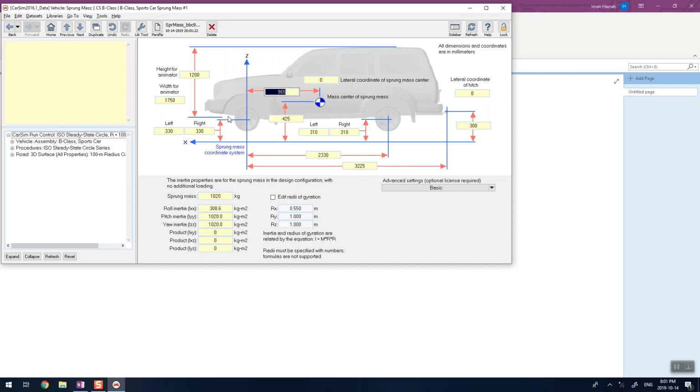You may notice that some parameters here are just for a graphical point of view, like the way you define the envelope for a vehicle to make animation around it. All of the units are in millimeters, and the total CG of the unsprung mass is here. I recommend taking a screenshot of this one, because you may need it for one of the questions at the end of the tutorial. And bear in mind that the reference coordinate system is assumed on the road and passing through the first axle.